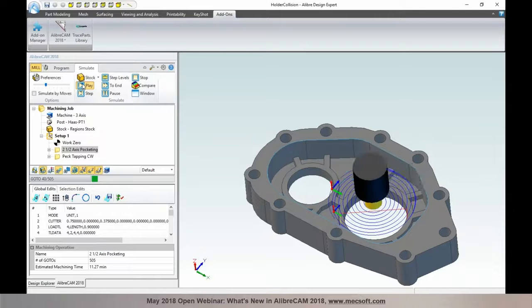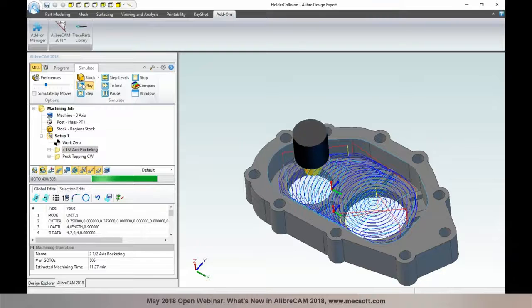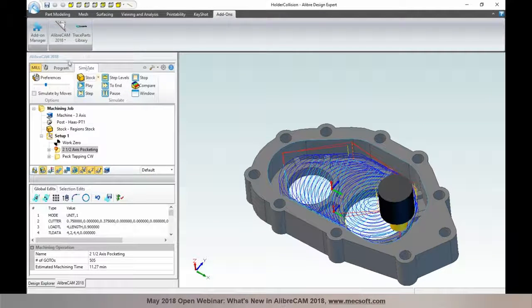Now, this is also available in slot machining. If you're programming a slot, it automatically does a high-speed cut pattern as well. You might have heard the term trochoidal machining. That's when we are machining slots using the high-speed cut pattern, that's in effect what you're getting. Basically, we're following a trochoid when we're machining that. So thank you, Uday. Thank you, Joe.